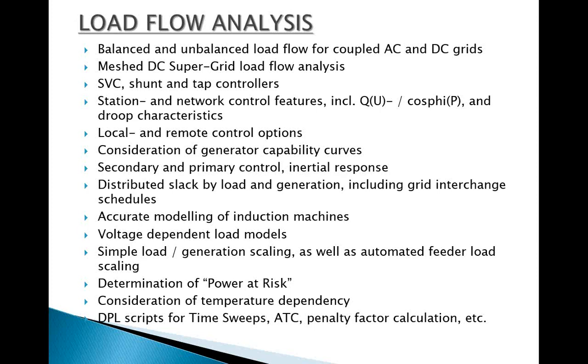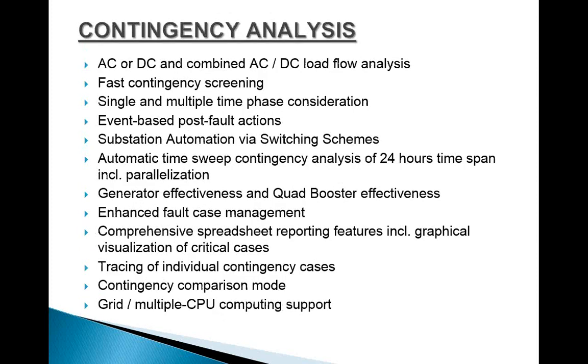Now contingency analysis. Contingency analysis comes with AC and DC, combined AC-DC load flow analysis. Also, a fast contingency screening test we can conduct. Single and multiple time phase considerations we can conduct. Event-based post-fault actions: we can give a particular section of the power system a fault over a particular period of time. That kind of command and event-based post-fault actions we can schedule on our own.